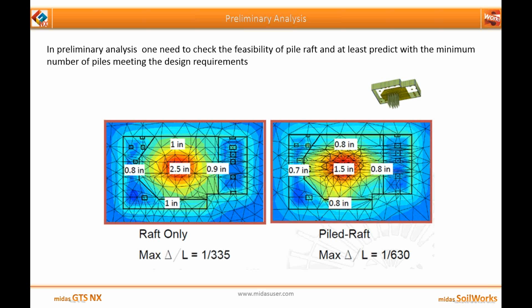We'll be considering two types of foundation, one raft only and the other pile raft, and we'll check what the maximum displacement is and what the differential settlement is which is occurring in our model. And we'll decide whether we should go for pile raft or raft only.